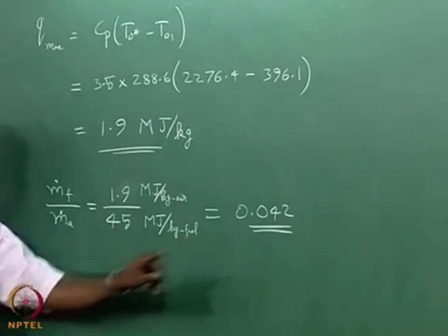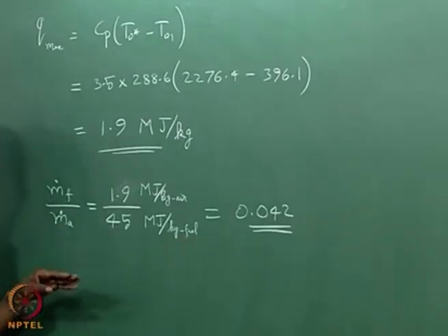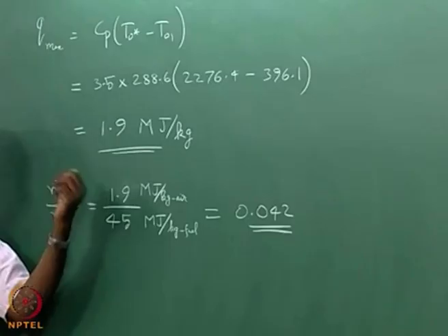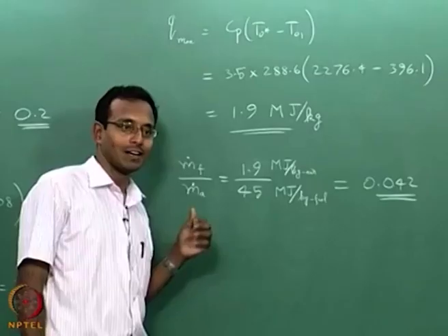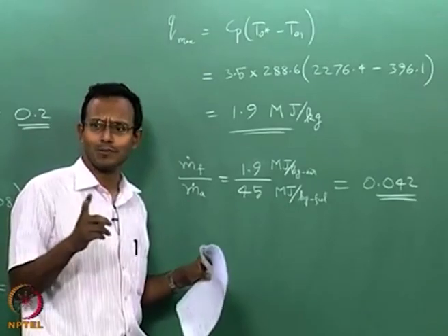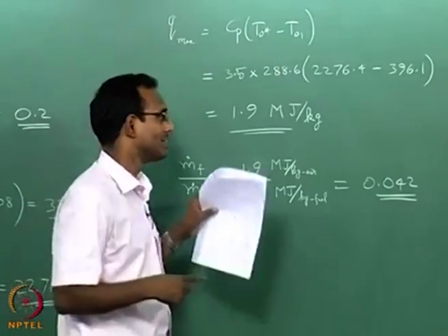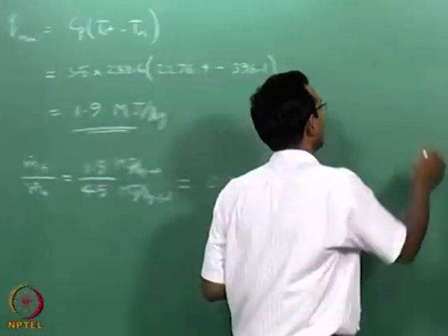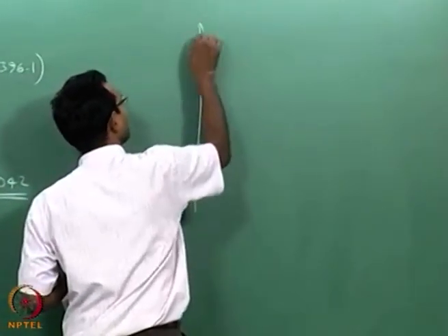That is, you are having thermal choking coming up suddenly, because I cannot heat any more. If I heat any more, what happens? I am going to have M equal to 1 forming, and suddenly the flow rate decreases everywhere and it jumps to a different curve. Oh, did I talk about that part? Maybe I missed that. So I will just go and do that one little thing, just a little detail.